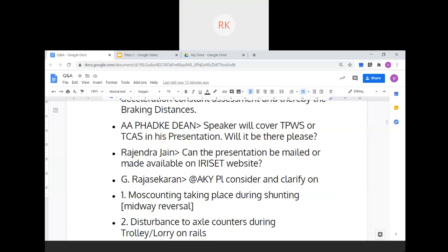There are far too many parameters to come to one deceleration point. Far too many. And the type of rail and wheel that we have here and what's used abroad, I don't know, the chemical composition could be the same. The slip and slide readings that came out of France or Italy and what came in India were totally different, and we could not generalize it. So we'll have to work on it, and it will take some time. But automatic braking distance calculation is a little ambitious, and I don't think we should get into it now. The doubt over, doubt under will be there. That's the element of safety.